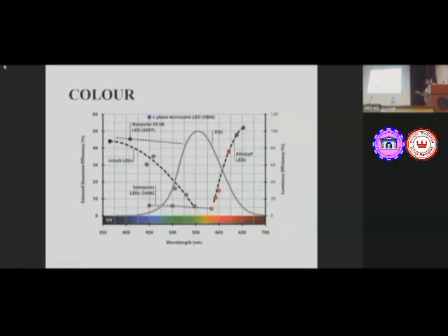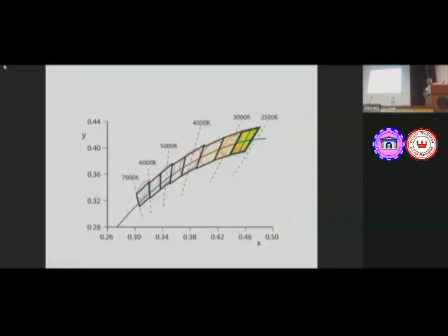And nowadays we are getting multiple colors out of the LEDs. If I talk about the white LEDs, that also we do get different shades of white. It could be cool white, it could be warm white. So in this case it is warm white, whereas when we talk about the bluish white, that is cool white. In between there it could be natural white. These are termed accordingly. This is placed on that chromaticity diagram. Okay, this is based on that chromaticity coordinate values, and the CCT parameter, correlated color temperature values, are also shown over here.